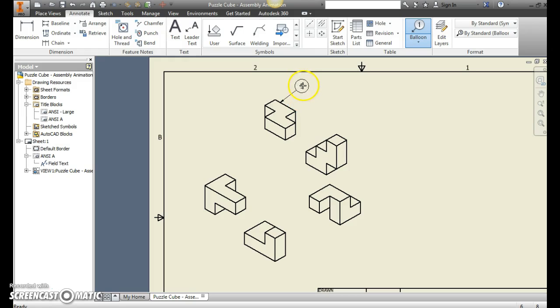So what you want to do is come out here a little ways at an angle and click, and then move your mouse to the right horizontally. Keep that line horizontal, and click again. And then from there, you can just right click and continue. And it'll put it back to where that last click was. So again, outside edge, come back out at an angle, click, and then pull it out horizontally a little ways, not very far, click again, right click, continue.